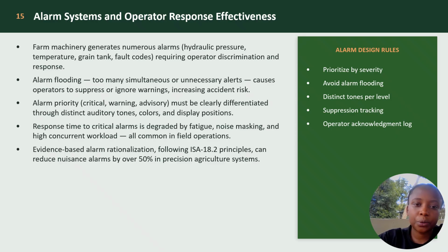Alarm flooding: too many simultaneous, unnecessary alerts cause operators to suffer or ignore them, increasing the accident risk. Alarm priority: critical warnings must be clear, differentiated through distinct auditory tones, color, and display positioning. Response time to critical alarms is degraded by fatigue, noise masking, and high workload, all common in field operators.